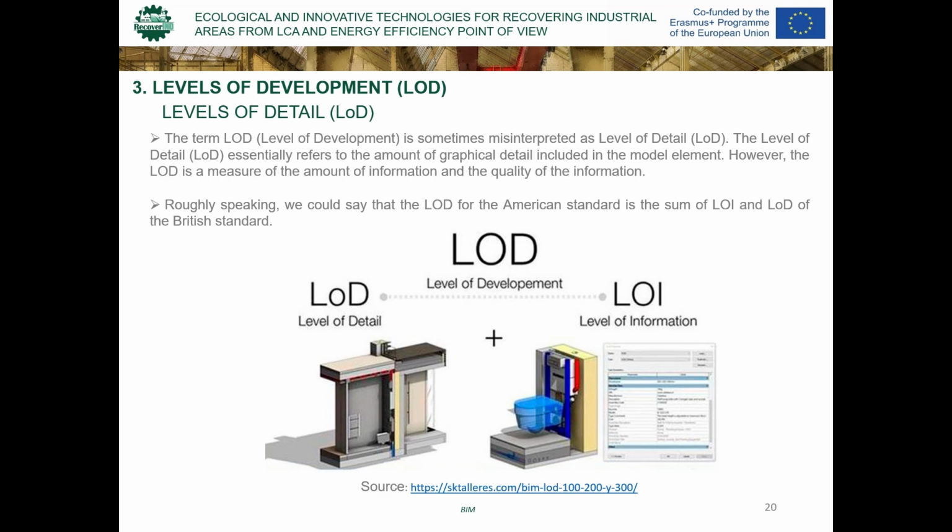G1 placeholder. Although it may be to scale, the object may not represent the appearance of the final component. For example, in the case of doors, this would be a simple, plain object without frames, vision panels or hardware. G2 suitable for construction. This is where the representative geometry of the final component would be provided. It may not yet include hardware, as this would normally be specified separately, but could be an object downloaded by manufacturers. G3 high resolution, fully detailed object. Normally only used for visualization or, indeed, for manufacturing.